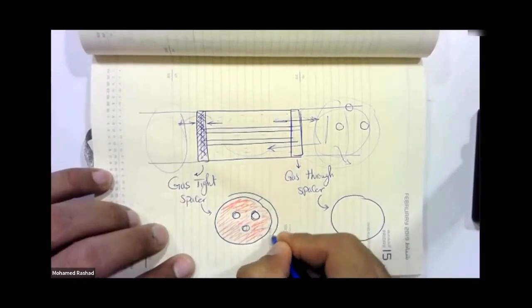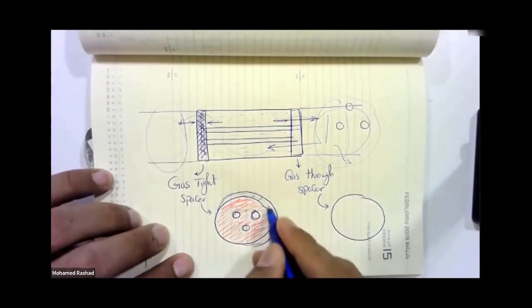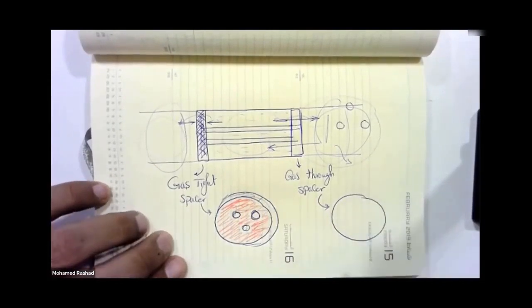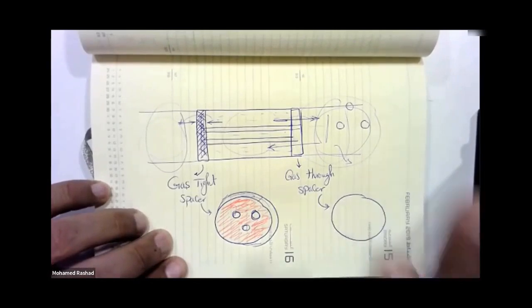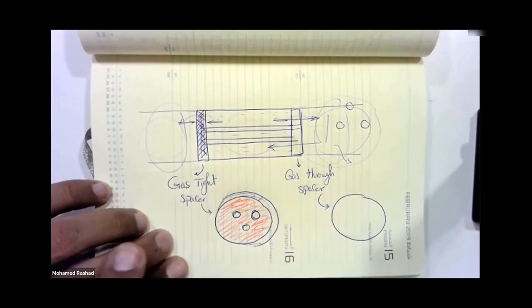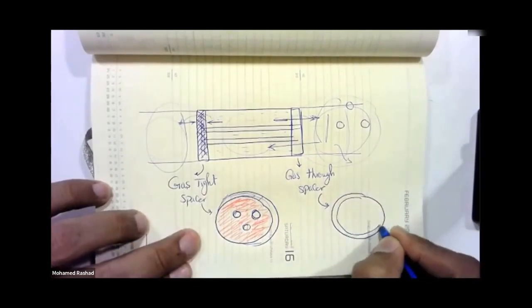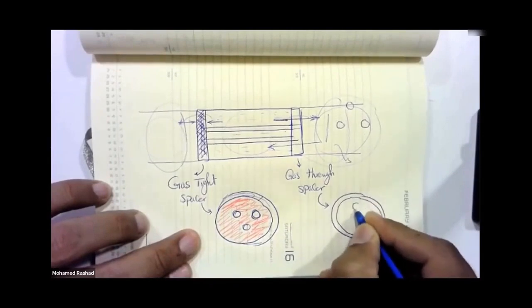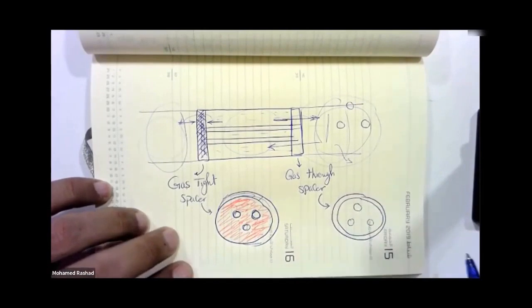It has thickness, of course, which is nice. I'm quickly sketching it for you. It has thickness like this, all right? So regarding the gas-through spacer, how is it structured from the inside? Of course, it can't be a solid block of epoxy with only 3 places for the bus bar to enter. No. Here, the epoxy is just the outer part like this. Now you have one phase, the second, and the third. How does it touch the support for them?